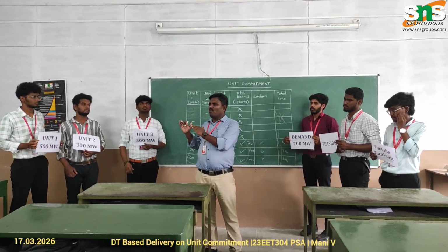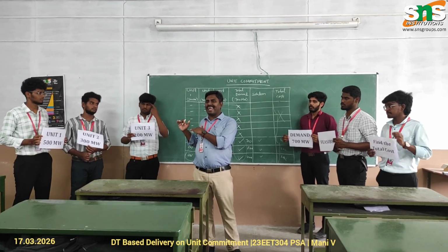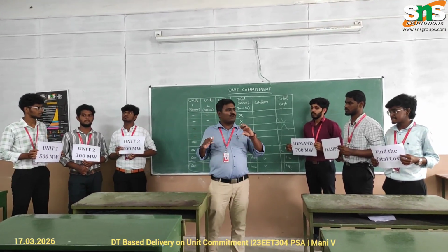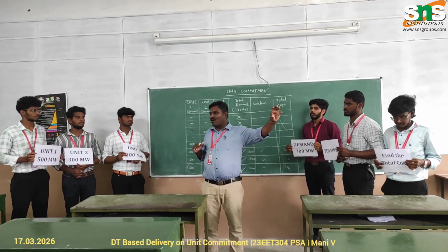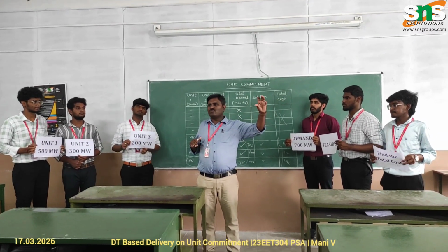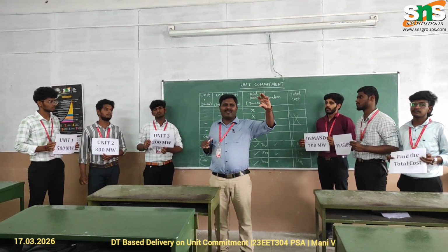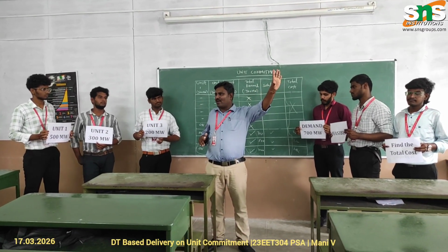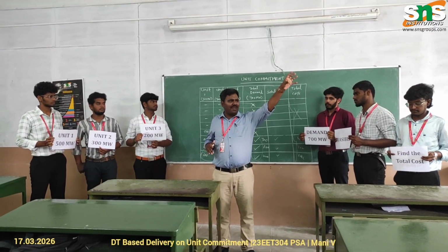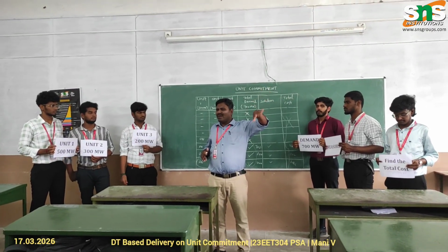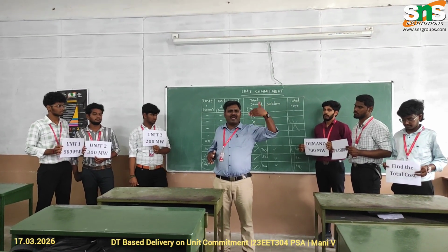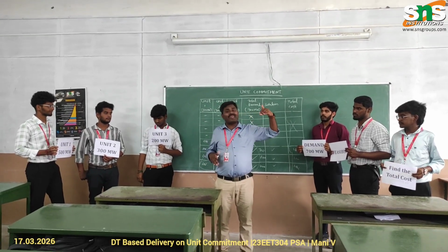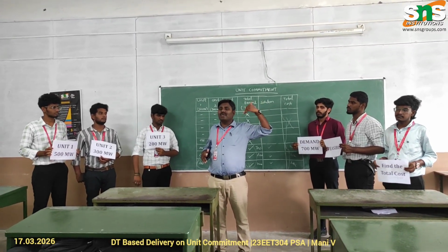So most thermal power plants can be used as base load, and for peak load we have to choose hydroelectric or nuclear power plants. Some power plants will be used only for peak hours of operation. If you turn on a hydroelectric power plant and open the penstock, the water immediately flows through the turbine and drives it. We start producing electricity without any time delay. So that can be used only for the peak hours.